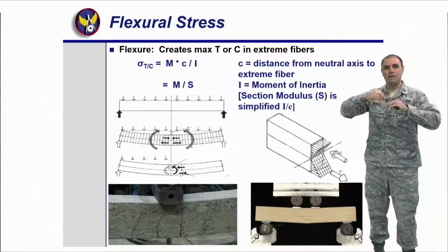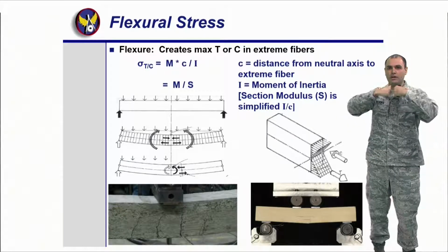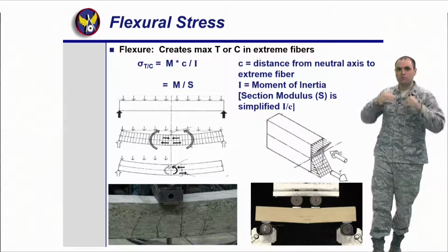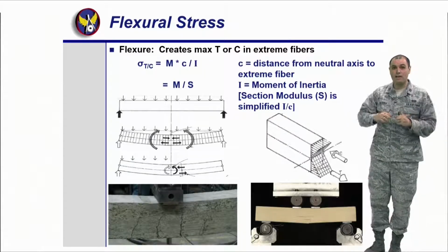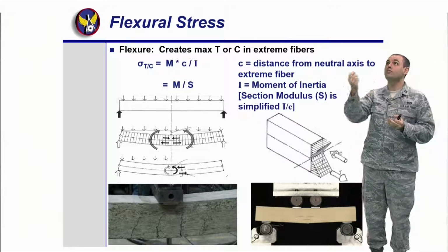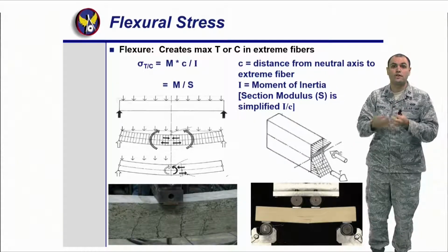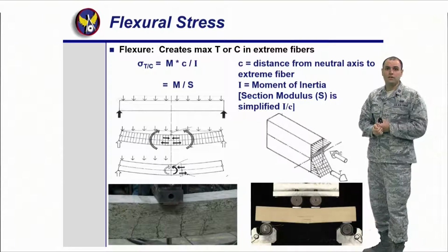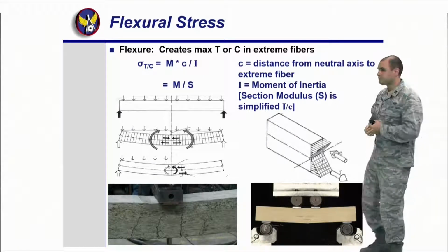When I bend the beam, in the top, everything is trying to get pushed together, right? All the internal stresses are trying to push together, while on the bottom, they're trying to be pulled apart. That's why when a beam is starting to have a flexure failure, you get to see all the cracks that are coming out, and you get to evacuate the building in time. Whereas, as I told you earlier, in the shear failure, you won't see that.